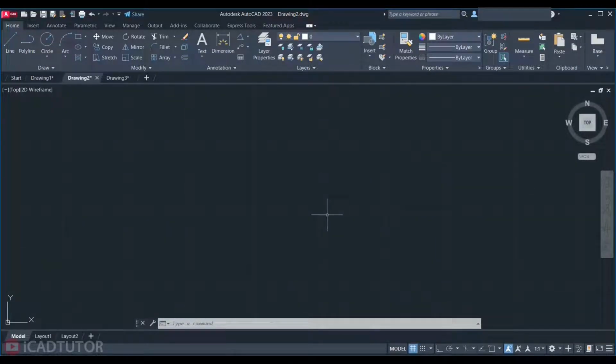Another point to note, look at here, I activated the line tool. Okay, here you see it says specify the first point, okay? Now, in addition to having the choice to specify the next point, I have another choice. I can specify the next point or undo. This means that in AutoCAD, depending on the tool we use and also depending on the steps we go forward, we will have different choices in brackets.